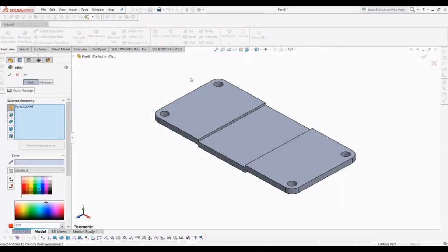After clicking that, it might take a while to open the PropertyManager here. In the PropertyManager, we are going to select which part to show the appearance on. This option is for which side of the part you want to set the appearance for. This is face. If you change it to this, you can select any face and change the color of any face you want. But now we are going to do it for the whole part, right? I think this is also going to be the select bodies option. So I'm going to select the bodies.